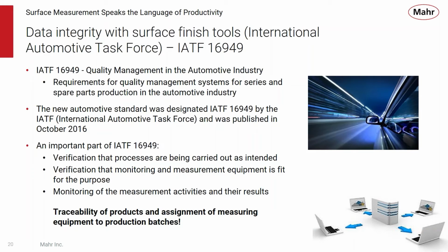So typically people will measure a part, they'll have a piece of equipment to measure it, they'll record the data, maybe get the time that measurement was made, and that file is complete. But there is a missing element to that. There's no traceability that the right instrument that's under calibration control made that measurement.